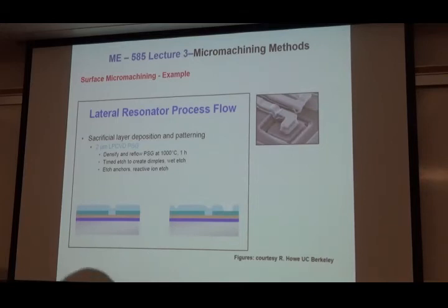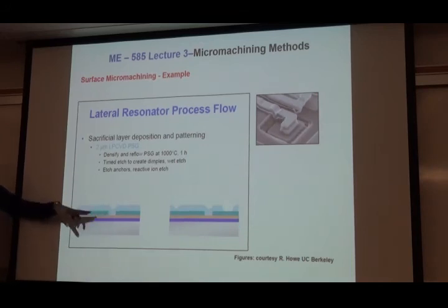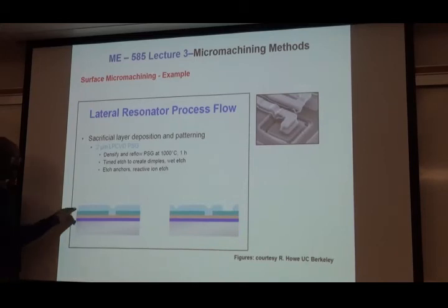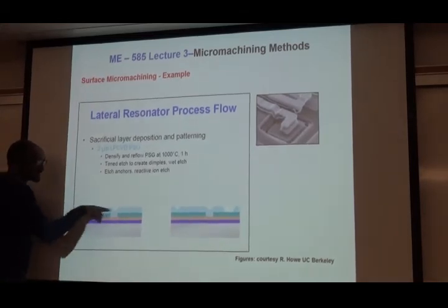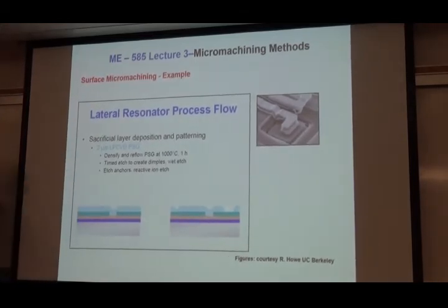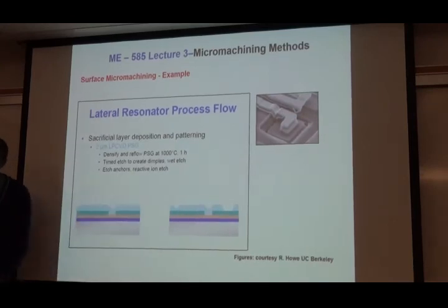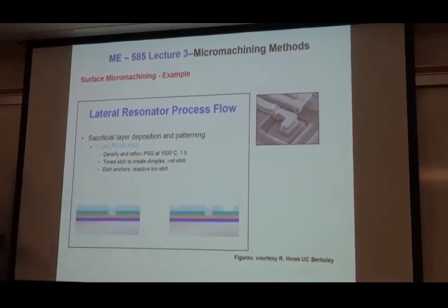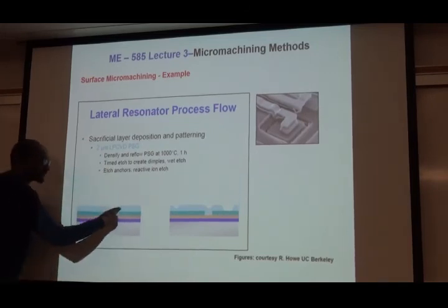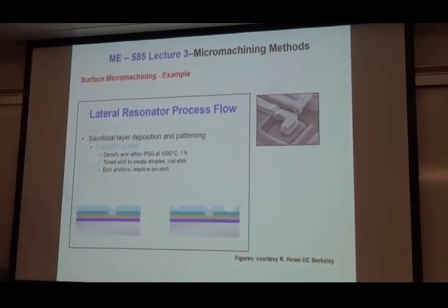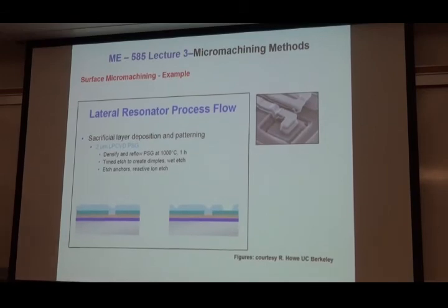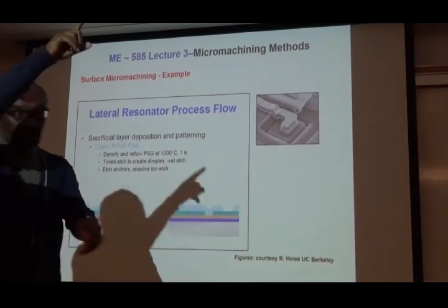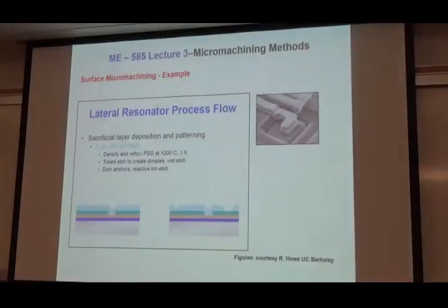Okay. Now, the first thing I want you to notice is, remember there was a hole here, you patterned. So when I do the deposition, when it fills it up, it's not going to fill it up in such a way that it's going to remain a plain, straight line. Because imagine you're putting a layer in a kind of a hole. What happens is it's going to fill it, and it's going to assume this kind of shape. Okay? That's why when you do homework number 2, you get shapes like that. They occur because of this.